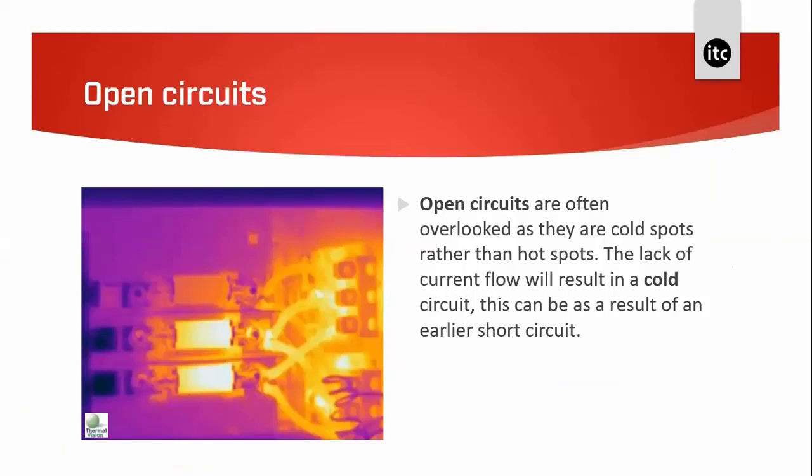And in this case, we've got an open circuit. The top fuse is blown. The fuses control a capacitor bank, and the fuse blew because of a problem with the capacitor. It's very easy when you're using a thermal camera to always look for hot problems in the thermal image. But with thermography, we can easily determine that one fuse is colder than the other. This is often the result of the fact that one of the fuses is not carrying any load at all.